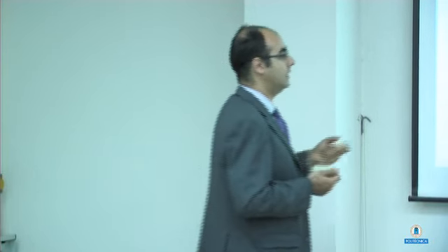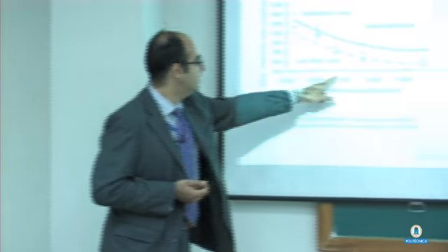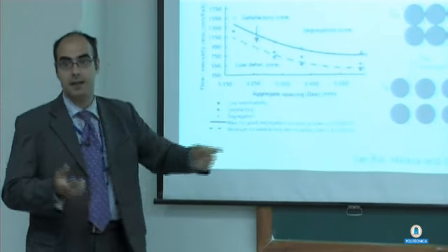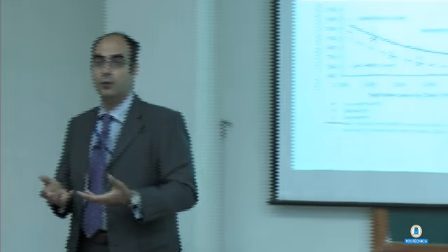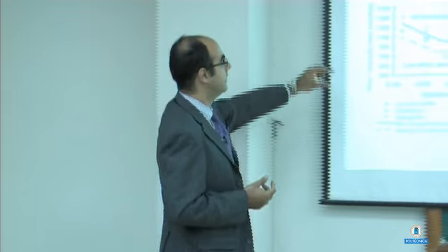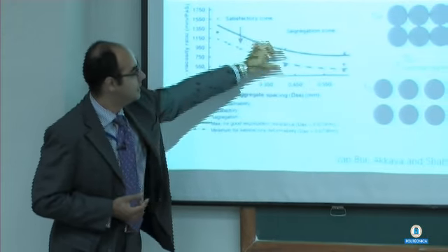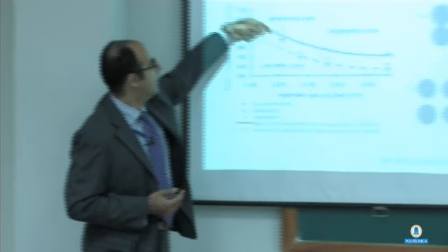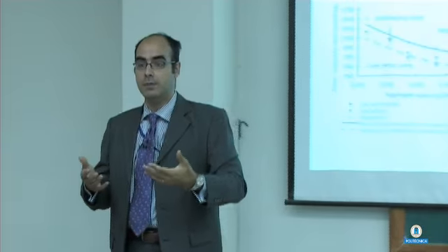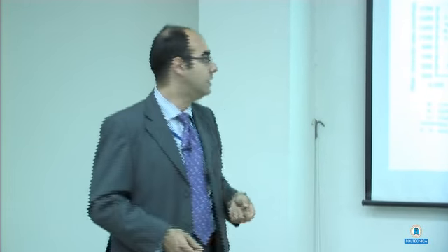While if you put in a lower amount of paste, so this aggregate spacing parameter becomes lower, you need a more fluid and a less viscous paste in order to achieve satisfactory performance in the fresh state. And you can see here the allowable zone is within this region. If you go here, you have a too fluid paste, so you have a too loose suspension, and aggregates may settle down, may segregate. If you go lower, your deformability will not be satisfactory, and you risk having a too stiff concrete.